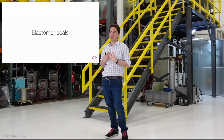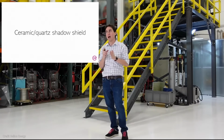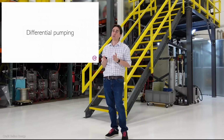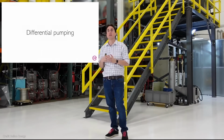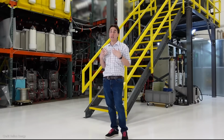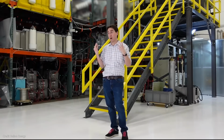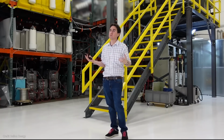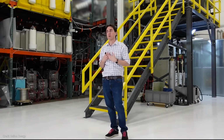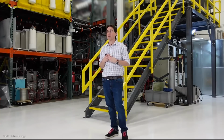So what we've been able to show here is we can build systems that have a quartz shadow shield interface on every elastomer, high temperature gasket, and then we differentially pump the backside of those gaskets to prevent, again, further leaks or any kind of interaction with any outside leakage. And then finally, by building these systems as robustly as we did, we are able to actually pump down these systems with a number of these seals and then stay under vacuum for 16 months straight and do several thousand, almost up to 10,000 operations of this system.